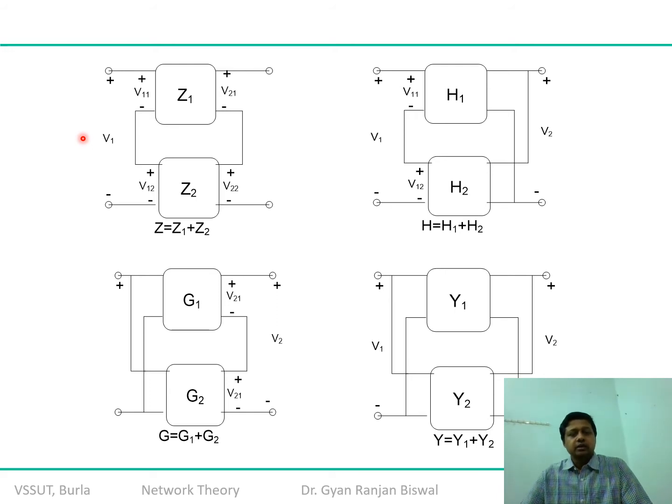So for Z1, rather than V1, because now you have two different terms, we will write V11 and V12. Remember, this V12 doesn't mean the backward direction. This is subscripting. V1 is the input, and the second subscript relates to that particular domain. So it is the Z1 subnetwork.